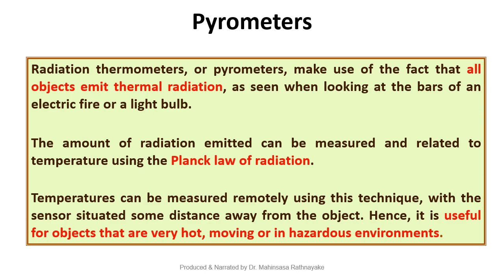All objects emit thermal radiation. The amount of radiation emitted by each body can be measured and related to the temperature using the Planck law of radiation. I hope that you have learned the Planck law of radiation. So the temperatures can be measured remotely using this technique. That is the most important reason why pyrometers are very famous in temperature measurement.